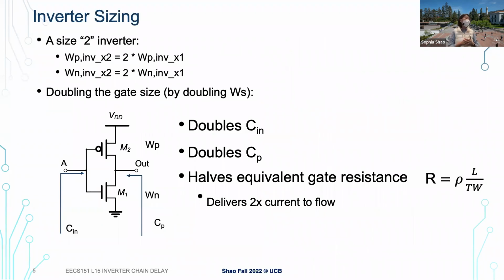We'll hear people talking about sizing, when they want to size a gate, size a transistor, size an inverter, or size a general CMOS gate. They are trying to modulate this width parameter that we just introduced. It's the dimension of our CMOS circuit, and that can change both the capacitance and the resistance of our circuit. For example, you may hear people say, let's put a size 2 inverter here, we need a bigger drive.